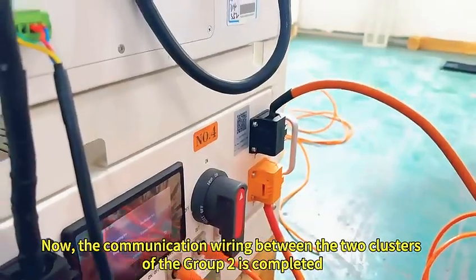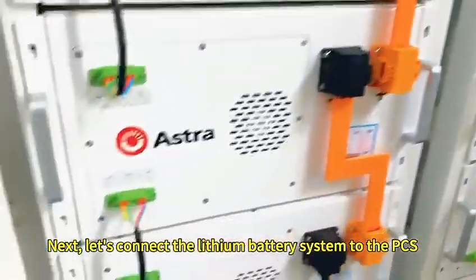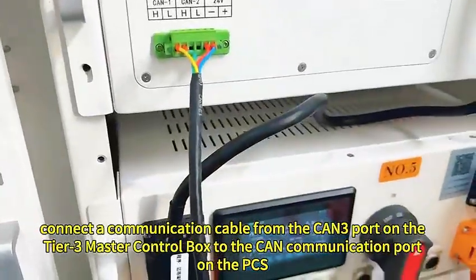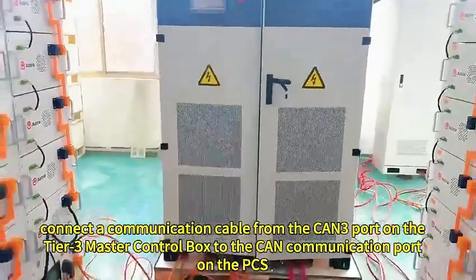Step 2. Connect the out port on the high voltage box of cluster 4 to the in port on the high voltage box of cluster 5. Now the communication wiring between the 2 clusters of the second group is complete.